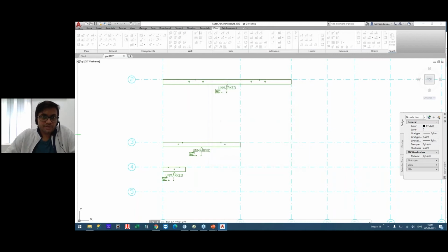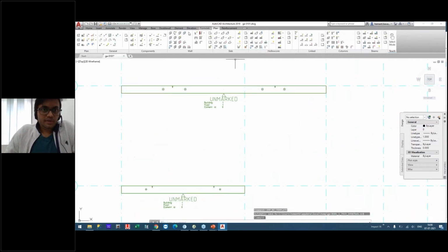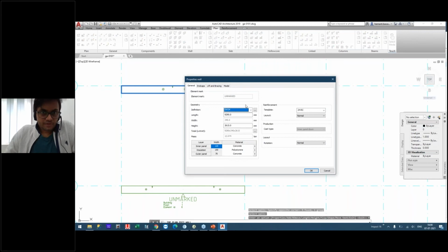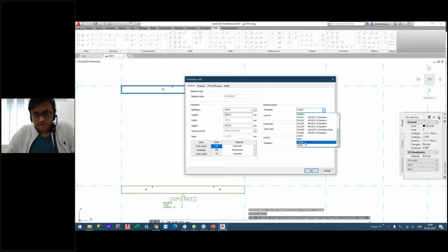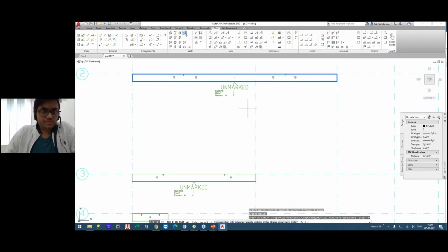Okay, then we will close our reinforcement template, and if I edit one of these walls, here I have chosen that particular reinforcement template, and it will be shown as the normal layout. By default in our definition it was 24 RC, but we just changed the name, so we had to select it again. Okay, and now we will save this wall.